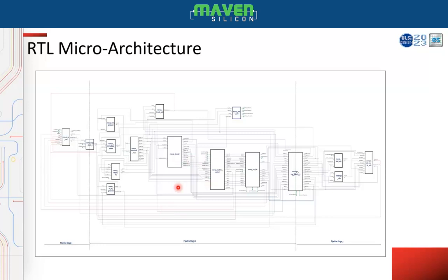So basically in stage 2, decoding the instruction and fetching the operands from that instruction will be done. At the same time, branch and store execution will also be done in stage 2 itself. And in the pipeline stage 3, executing remaining instructions and writing back the results of those instructions will be done in the pipeline stage 3.